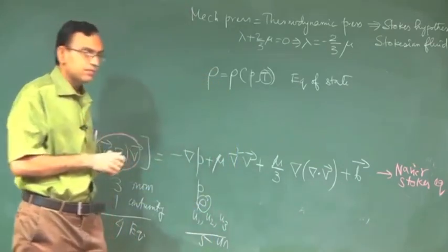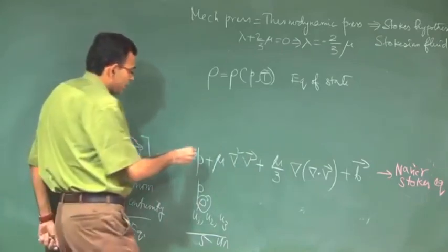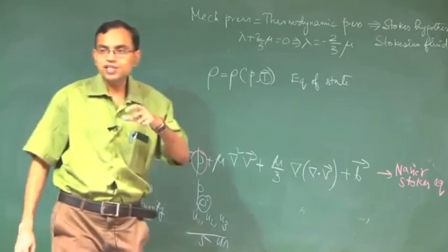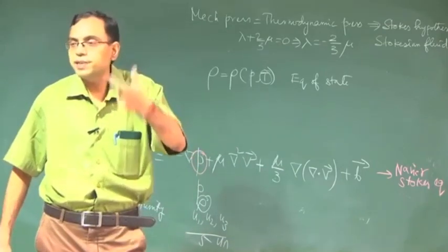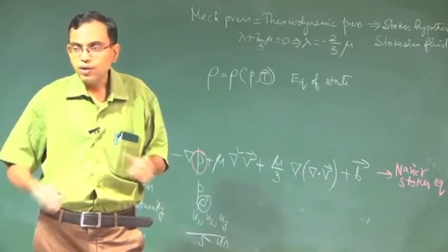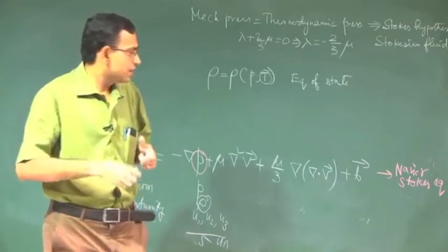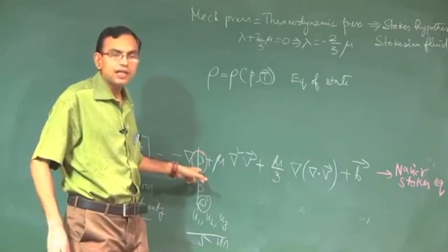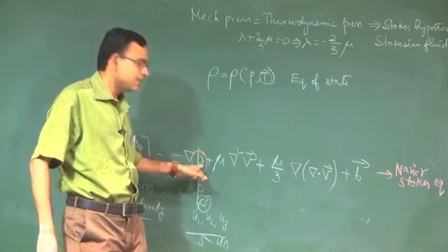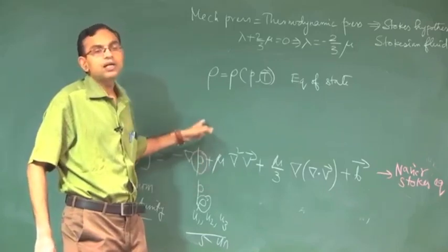The other issue is that there is pressure as a variable, but there is no separate governing equation that explicitly governs the variation of pressure. So the only way is that either you eliminate this pressure in some way or the other, or you link this pressure with the continuity equation.